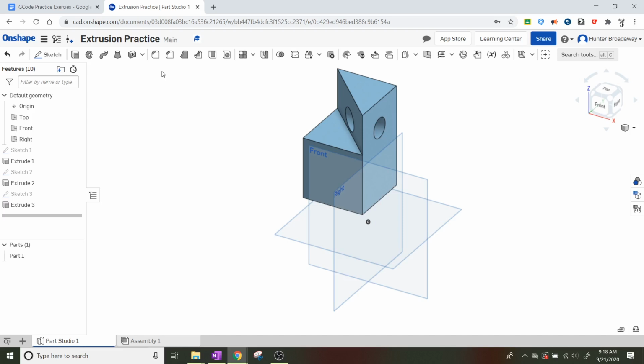The order that you guys do this in is important. Before you start messing around with how far you want it to go in or out, my recommendation is to always pick add or remove first, and then decide how far you actually want it to be added or removed. Because for some reason, if you do it the other way around, sometimes it gets confused and comes up with errors or won't work at all. So I would pick add or remove first, and then dictate how far that actually goes backwards or forwards. Okie dokie? Does that make sense to y'all?